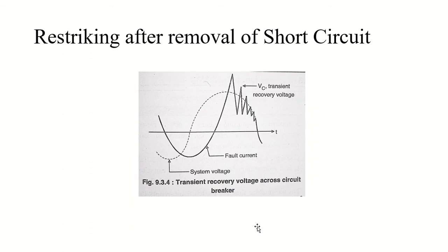And to understand that, see this figure. It shows the transient recovery voltage across my circuit breaker, which is given by vc here, and you can also see where the fault has occurred and what the actual system voltage is here, right? So once we remove the fault, the source will change. The source charges the capacitance, and the inductance of the circuit causes an overshooting of my voltage. The system losses will damp the oscillations during this period, and the voltage vc will be the transient recovery voltage.